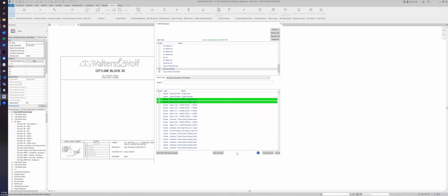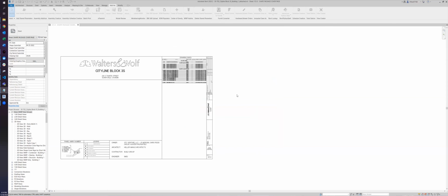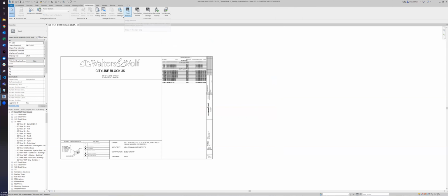If you want to send, you would click save and send. That will save your changes and send them up to BIM 360. But if you just want to save and not send, you would just hit save and close. A little notification next to the save and close button tells you what sets are about to be modified on save. Let's double check, make sure you have your sets modified to how you want them, with these two views on that set and these two views on this set. Let's hit save and close. And it'll take a few seconds to apply the changes.